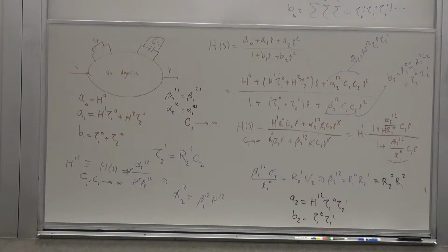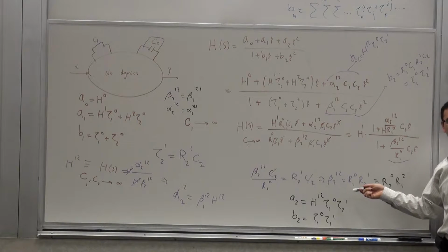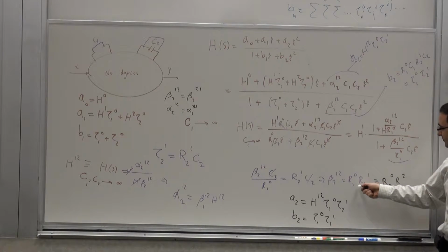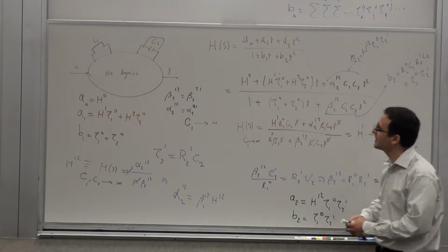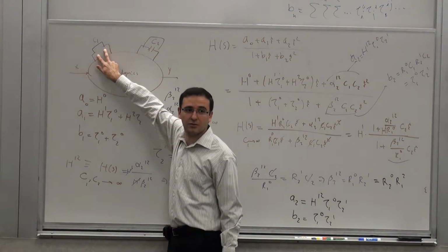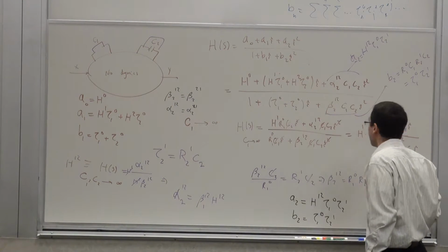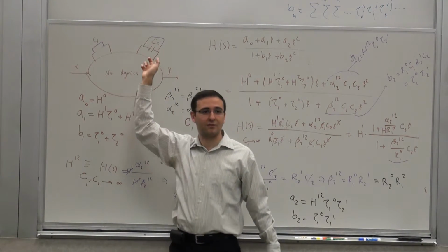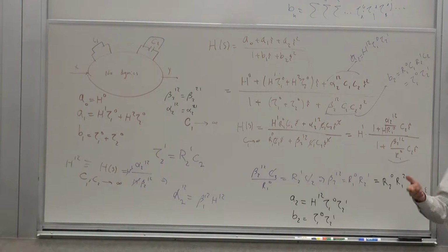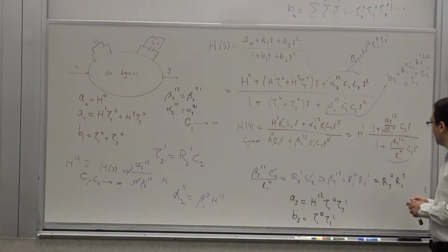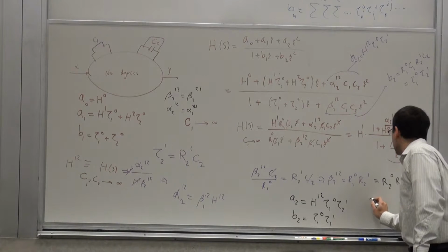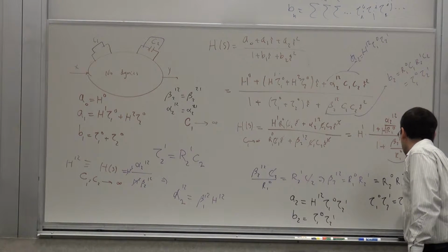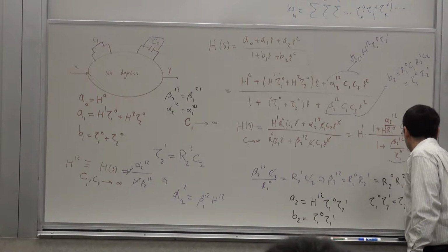Now, while these are just indices here, these are two different calculations. It means that you can calculate this resistance, which is the resistance seen by this guy when this is infinite value, or you could calculate the resistance seen by this guy when this is infinite value. And this product should be the same, and you will see that they are the same when you do the calculations. I'll just show you some real practical examples. And moreover, what that means is that tau 10 tau 21 is equal to tau 20 tau 12.